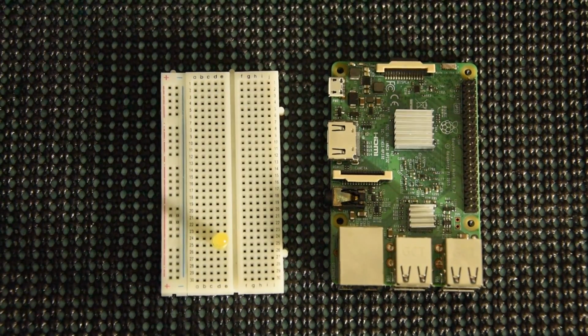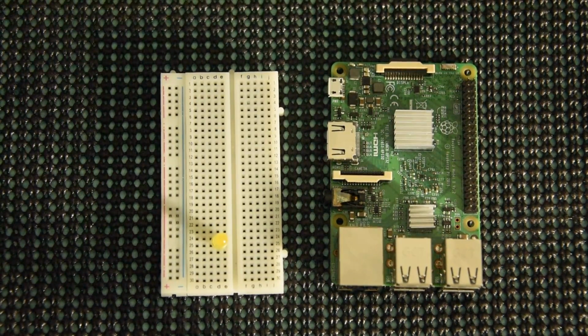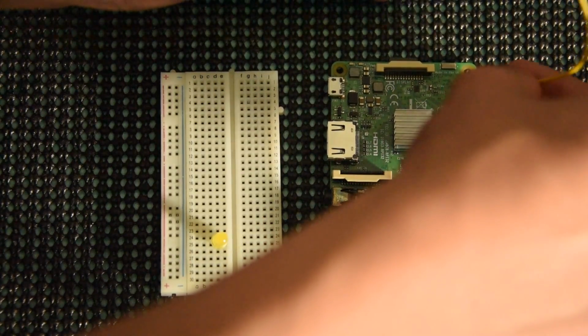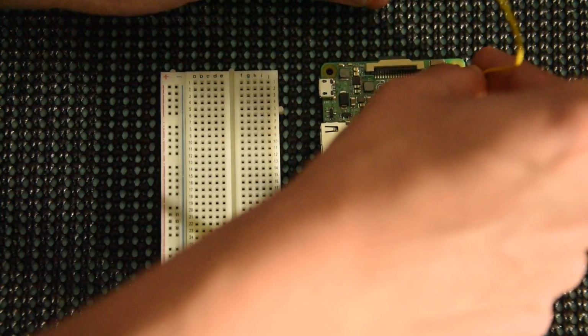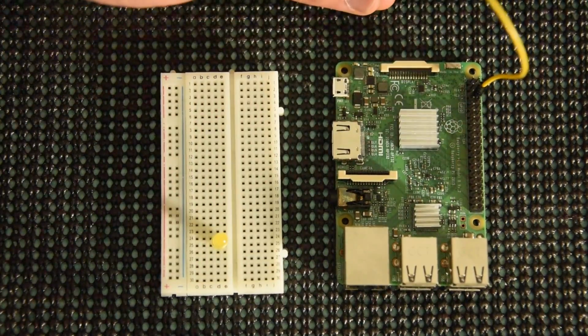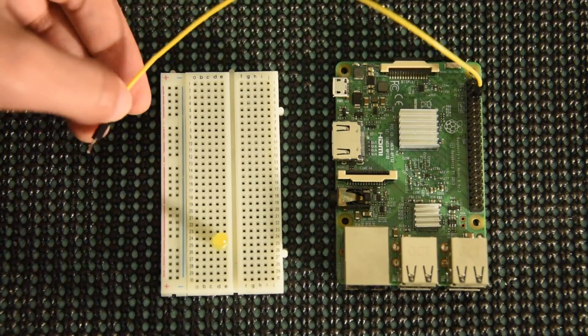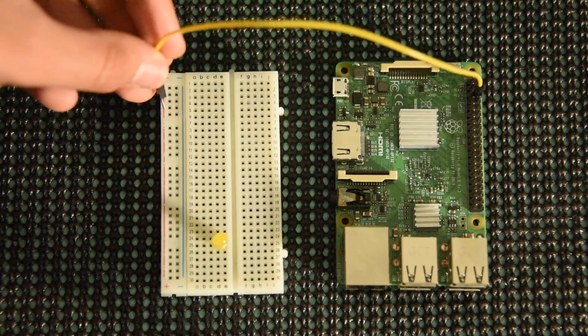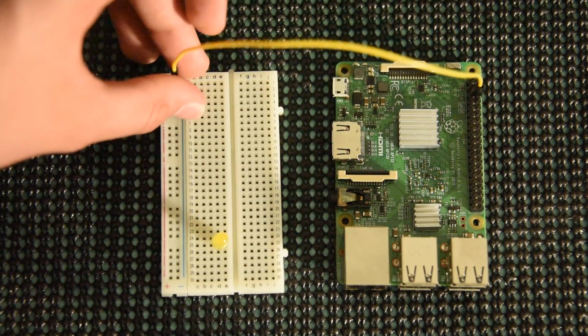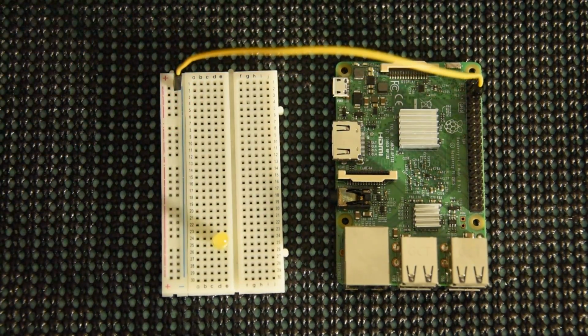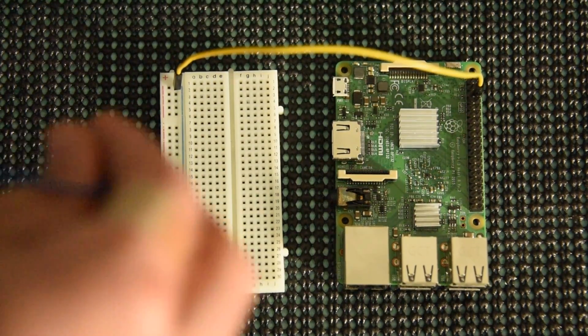Before we go programming, we need to wire our circuit together. Luckily, this is pretty simple. First, connect your LED to the breadboard, making sure to remember the long and short wires. After that, connect a pin from ground to the negative side of our breadboard. This is what's known as a bus, which we can use to transmit ground data to any pin on the negative side of the breadboard. So for example, if we take that negative side and connect a wire to it, we can transmit that ground data to anything else, such as our LED.